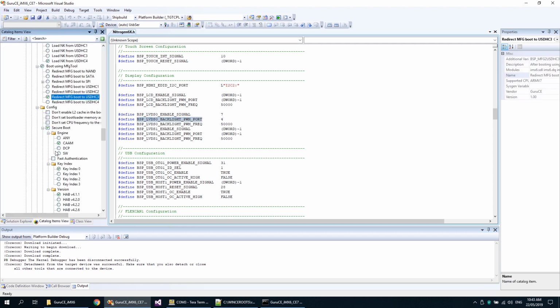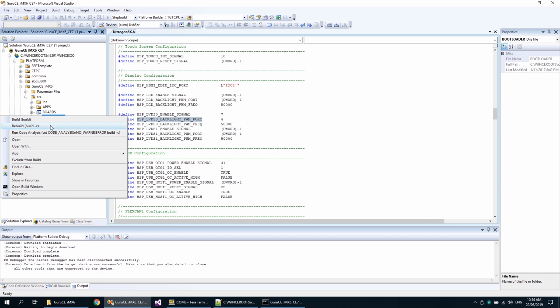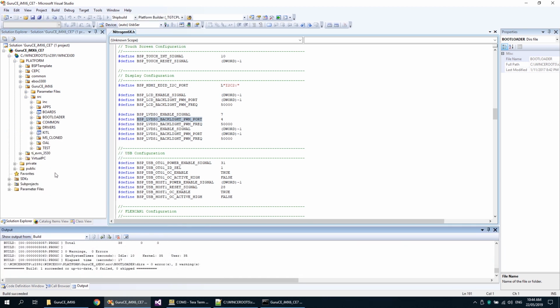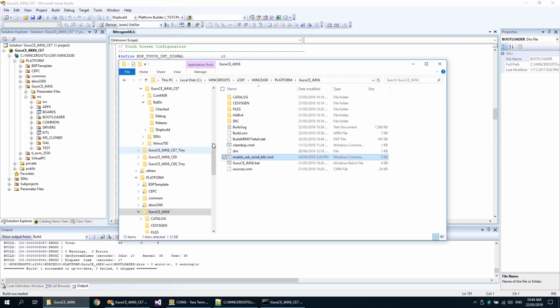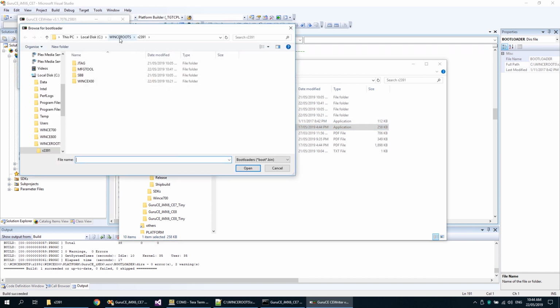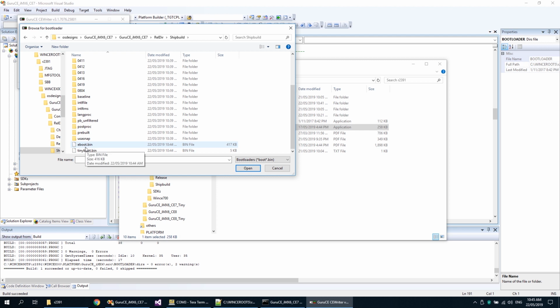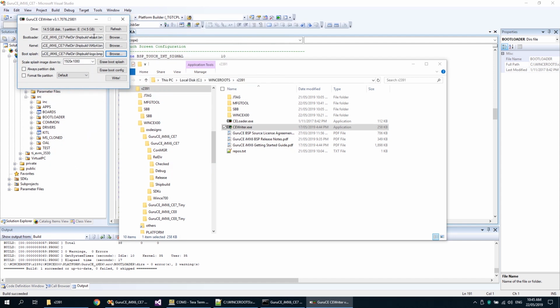First, reset the BSP Catalog to build a bootloader destined for SDMMC and rebuild the bootloader again. Insert an empty SD card in a card reader connected to your PC. Start CEWriter and click the Browse buttons to select the bootloader, kernel and boot splash images from the flat release folder. Make sure the correct drive is selected and click Write to write everything to the SD card.